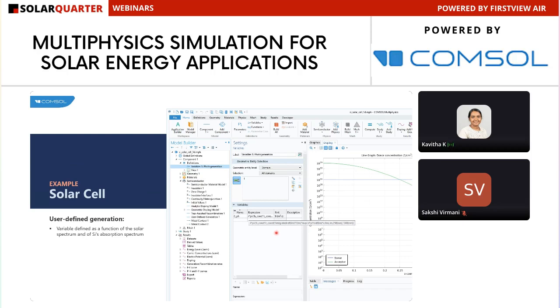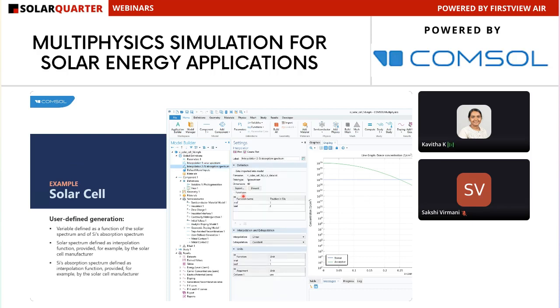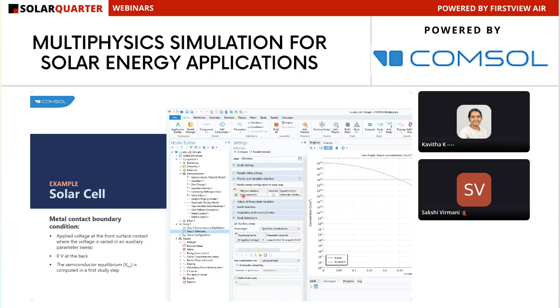Here you can see the variable used to define the generation rate, which is a function of the solar spectrum and a function of silicon's absorption spectrum. The solar spectrum is defined as an interpolation function. So if you have the material properties as a function of frequency or wavelength, you can import those material properties. So for the solar spectrum, we can define it as an interpolation function as provided by the solar cell manufacturer. Also, the silicon's absorption spectrum is defined as an interpolation function.